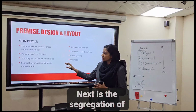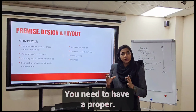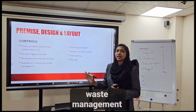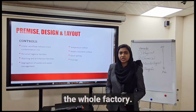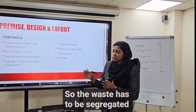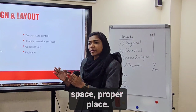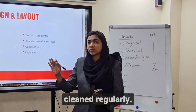Next is the segregation of waste and waste management. You need to have proper waste collection bins. Those bins have to be emptied regularly, and you have to have a proper waste management system. You cannot drop waste here and there, contaminating the whole factory. So this can be a source of major contamination. So the waste has to be segregated from the raw material, finished product, vessels, everything. The waste needs to have a proper place where it can be kept and emptied regularly, cleaned regularly.